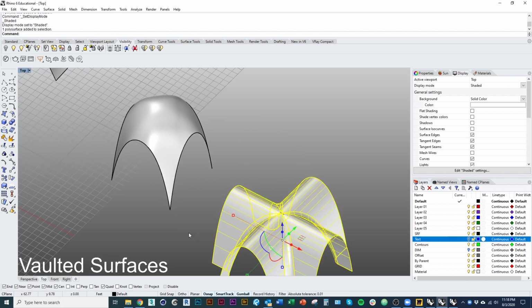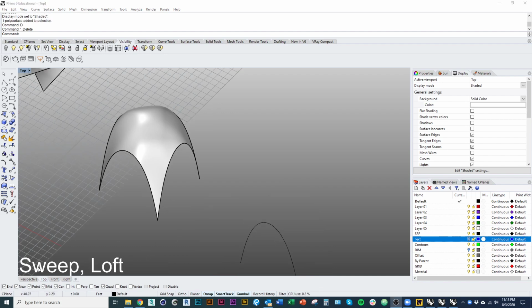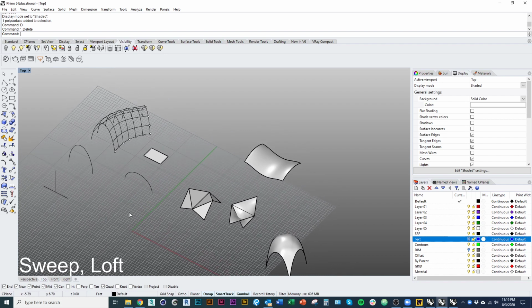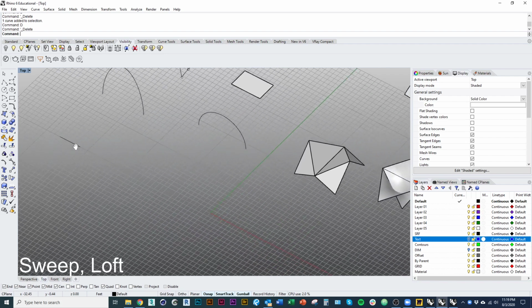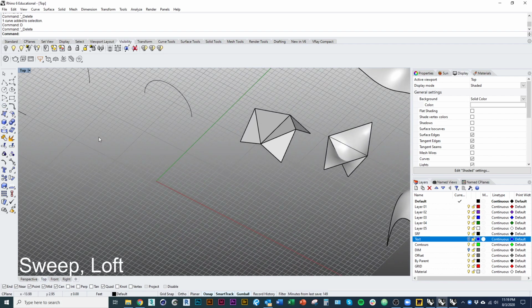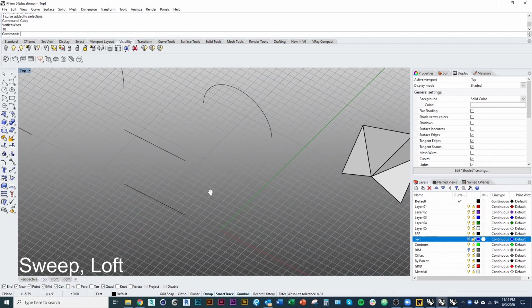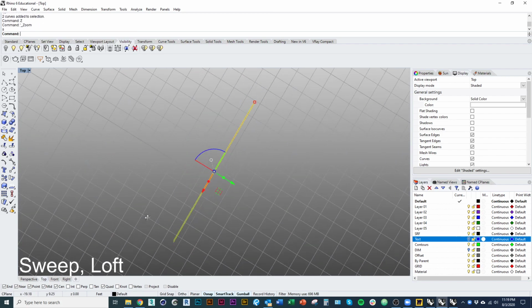The other thing I wanted to mention is that, like other examples from certain case studies, we can make ribbon surfaces by twisting. So for example, let's say I had a set of curves that I wanted to make strips in between. I'm going to draw one curve like that, and I'm just going to copy it. With the move command, I can use the option vertical to move it up by 10. Okay, so now I have two straight lines, one right above the other, in 3D.